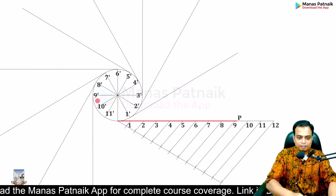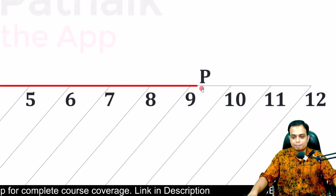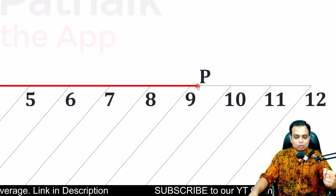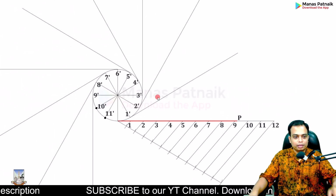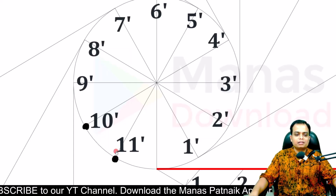Now, sir, why haven't you made tangents from 10 and 11, or 10 dash and 11 dash? The reason being very simple. Our free end, P, is going to end somewhere very close to 9, just beyond 9. So you don't have to go for 10, 11 and 12. The free end is going to end somewhere here, to be very precise. So you don't have to make tangents through 10 dash and 11.